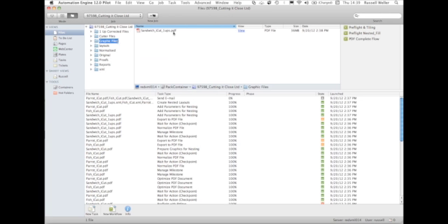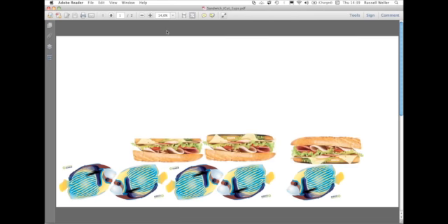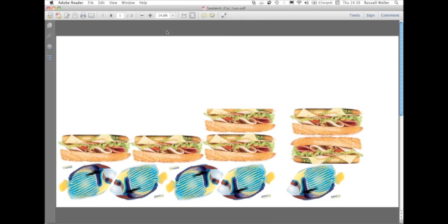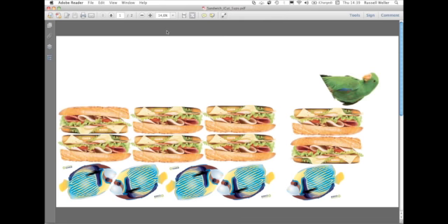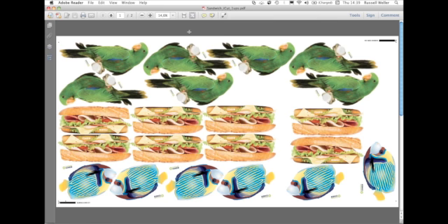So just while I was explaining that part, that's now finished my layout file. What's that done for me? Let's have a quick look here. Fantastic. So here's my graphic file. You can see I've asked it to lay it out in any order on my sheet. So this is really now doing some irregular shape nesting. It's not taking the trim box, so I'm really getting the best usage out of that particular sheet. You can see some nice nesting going on here.